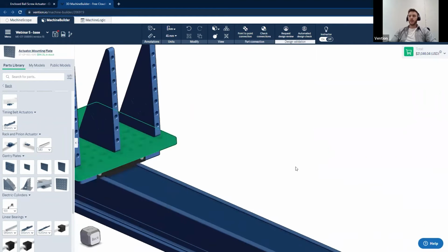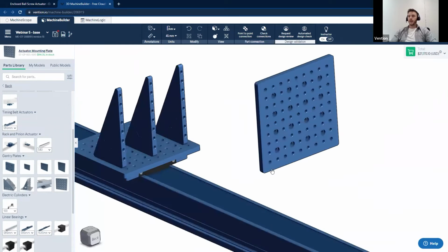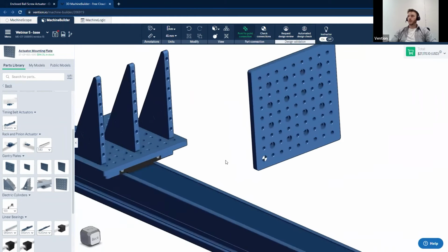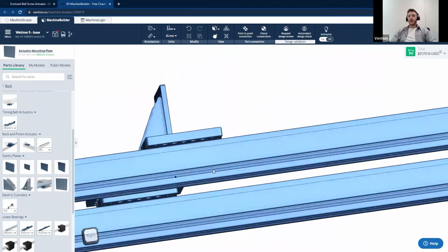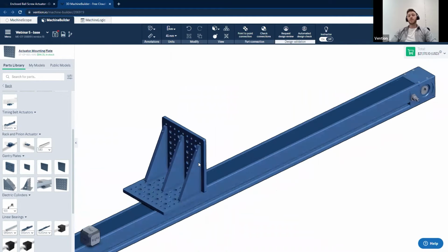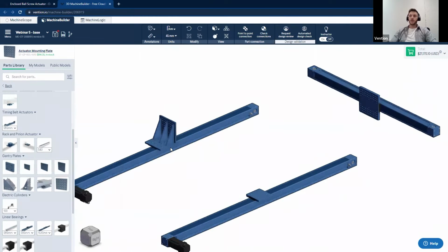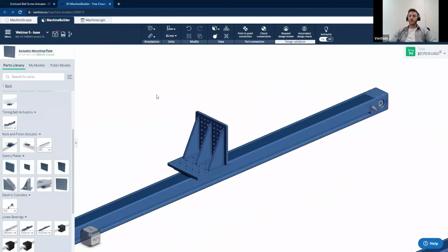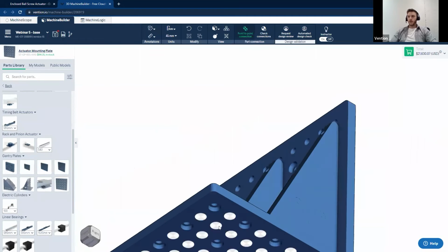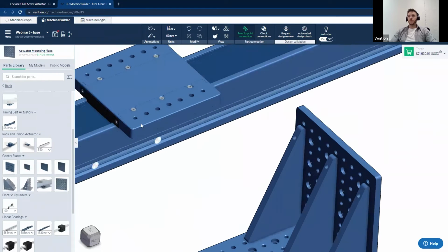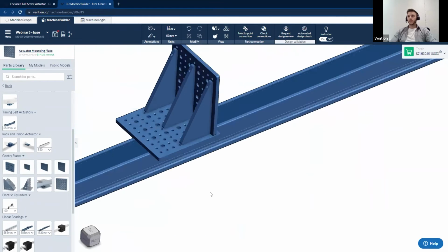Finally, I'll click on the gantry plate and insert it into the design and attach it to my structure. So with this, I'm going to select the corner over here and attach it. So that we've now completed a location to mount our horizontal, our x-axis, on. However, we only have it on one of the two. So again, I'll use the copy paste feature by selecting the hardware that I would like to copy, pressing Control-C and Control-V to drop it down into space. Again, point-to-point connection, just for the speed of designing and attaching it there.